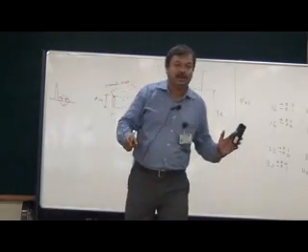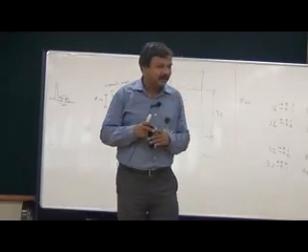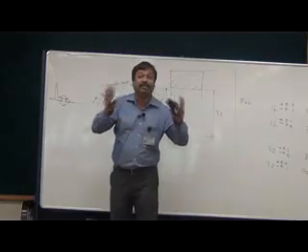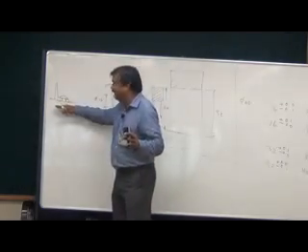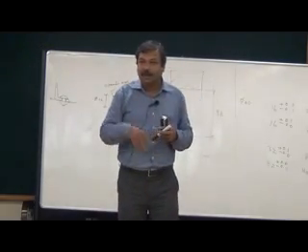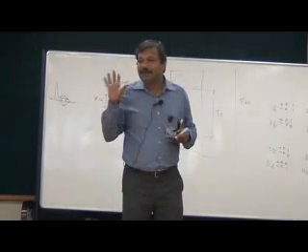It will very easily go into the hole because it is shrunk. The diameter is smaller. As it is taken out of liquid nitrogen, it will be very soft, so I can very easily deform it and form it in the hole. I can leave it. What will happen? The rivet will slowly expand and close the gap.